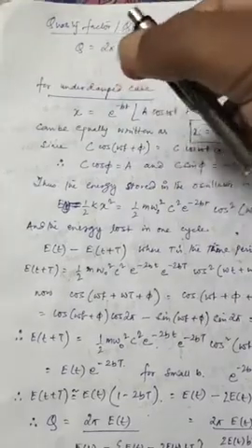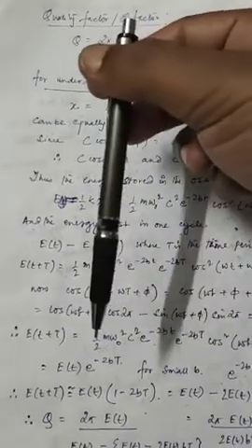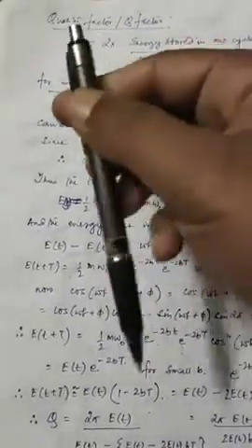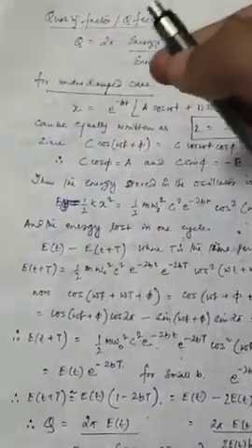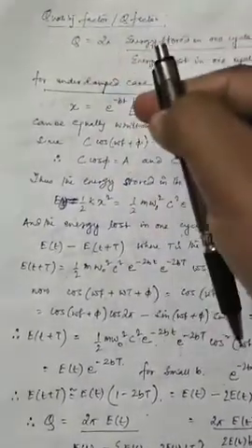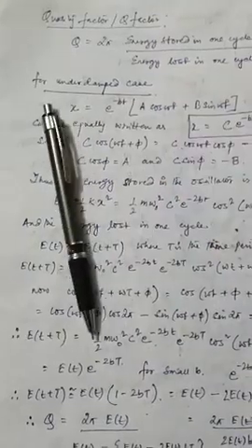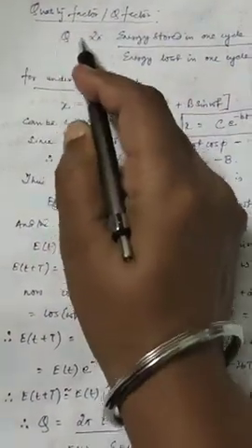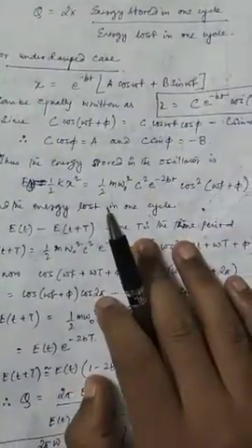So see, if the system is oscillating like this and it oscillates, let's say, 100 times before its energy reduces to a considerable amount, then the quality factor is telling you how many full oscillations take place before its energy is reduced considerably. But let us say if the damping is very large, maybe the system would oscillate, say, 20 times and the energy would go down considerably. In that case, the quality of oscillation is going to be very low, since the energy lost in one cycle is going to be very large.